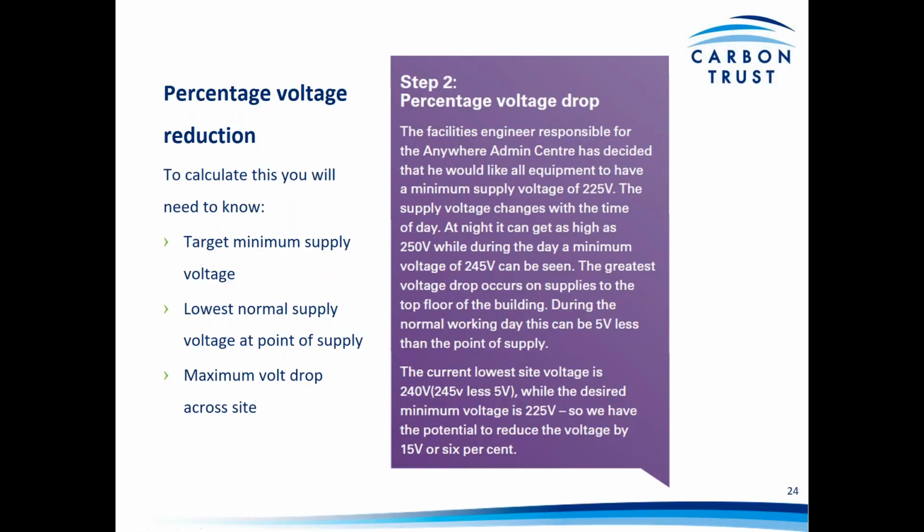Just one thing to point out on that slide. If the demand that we actually measured during a site walk around, by taking actual measurements on site, was greater than what we had just calculated as the combined maximum demand, then we would probably need to carry out another walk around and make sure that we hadn't missed something or underestimated the loads.